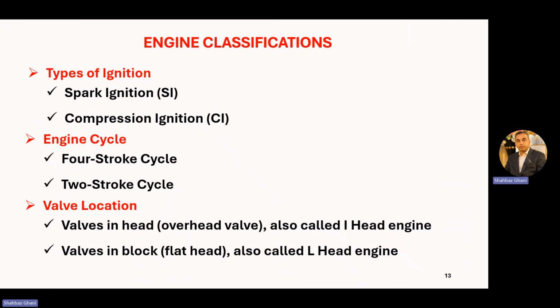Okay. Now, with respect to the valves location, the valves are the inlet valve and the exhaust valve. If the valves are in the head, we call it overhead valves, also called I-head engines. If the valves are in the block, we call it flathead, also called L-head engines.